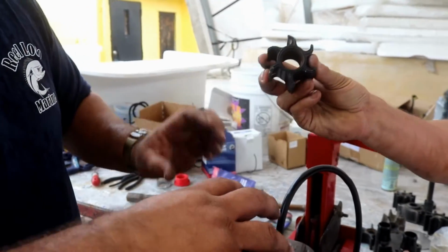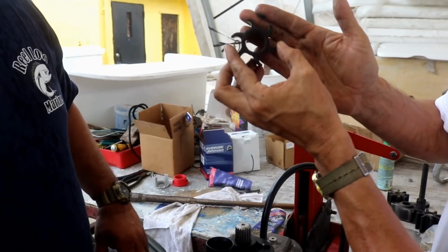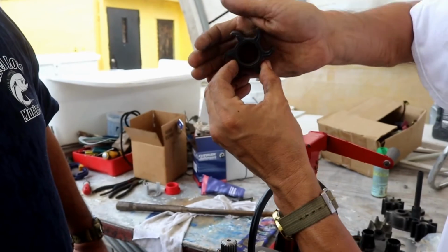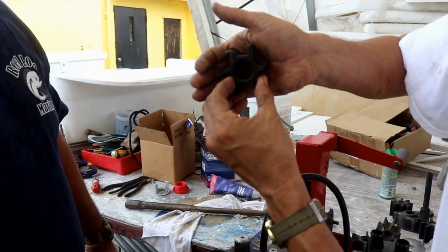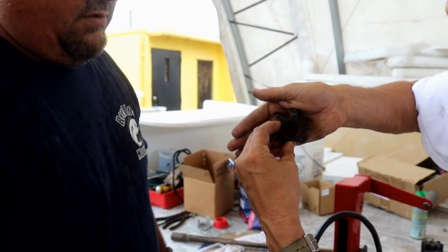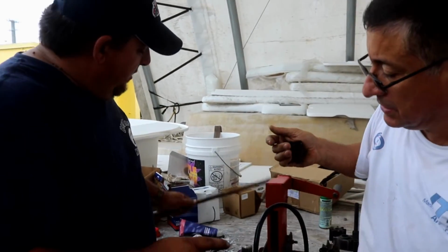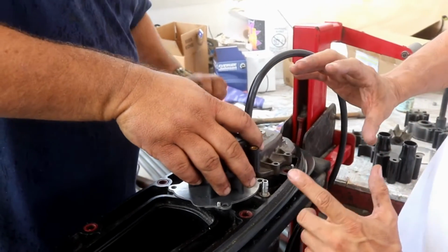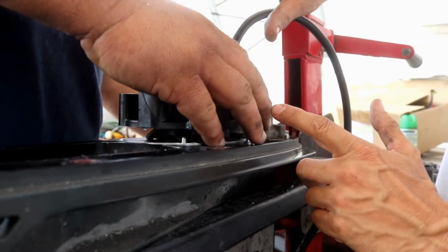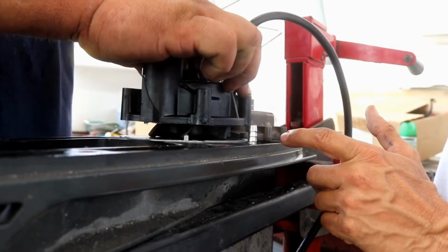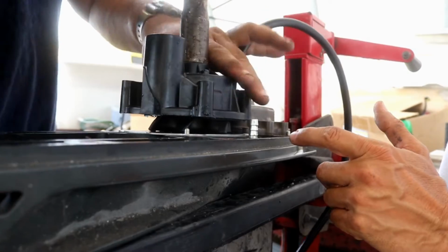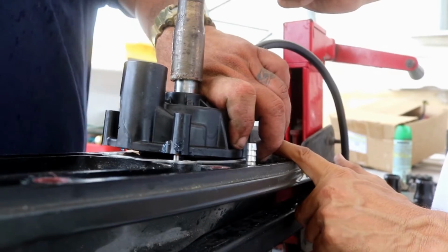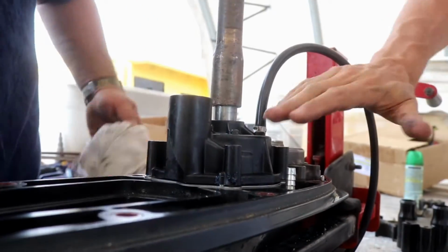So when you put the impeller in, you have to spin the housing. Okay. If the rotation is clockwise, it's spinning like this, and you should turn the housing in the opposite direction a little in order to help that introduction. Correct. And once you get it low enough, then you can put this on there and twist it by hand. Okay. We are going to do the process slowly in order to show the process. And exactly. Right now, it sits properly.